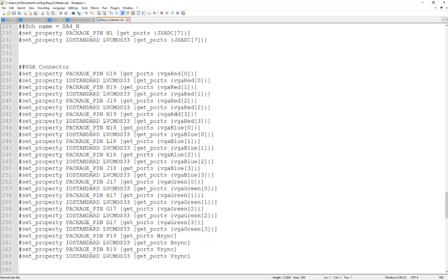But eventually we are only having 8 bits in total. Keep in mind, 8 bits in total. You have 3 different colors, right? 3 times 4 becomes 12. So you do have 12 bits to resolve all 3 colors, R, G, and B. But the thing is, we are not using all the 12 bits. We only use 8 bits to resolve the colors in the picture, which will result in what? A poor quality of the picture.